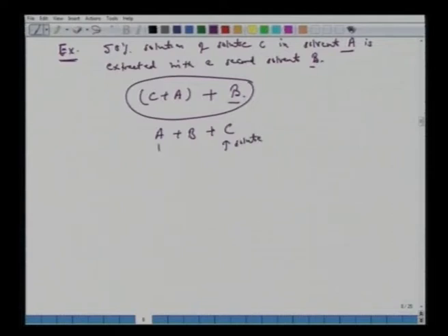So now it says the weight of B; all it means is that even the flow rates will be in the same ratio. So S by F, maybe. This is solvent B, in the previous nomenclature S, so S by F is essentially 0.25. It is kg per second here and kg per second there. Although it says the weight of B is 25% that of the feed, essentially it has the same meaning: S by F is 0.25.